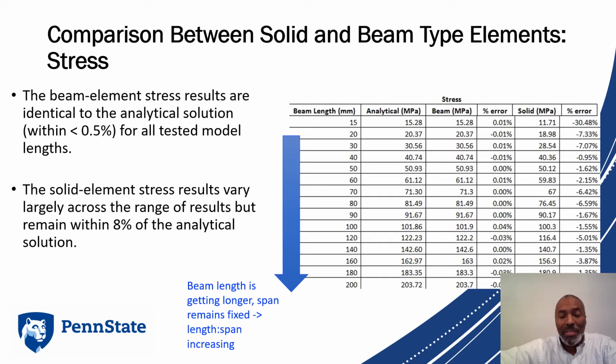For the solid elements, when you eventually begin to look at solutions for finite element methods, when you take that class here, what you'll see from the mathematics is that the equilibrium equations are only satisfied in an integrated sense. Because they're only satisfied in an integrated sense, you can have variations in the solution with respect to the actual analytical result.